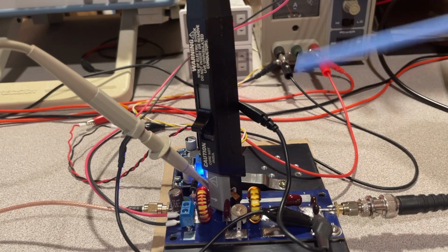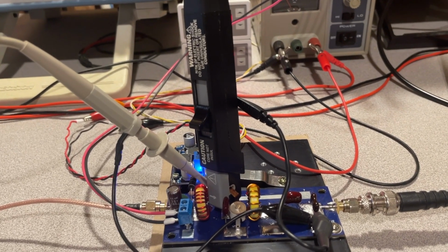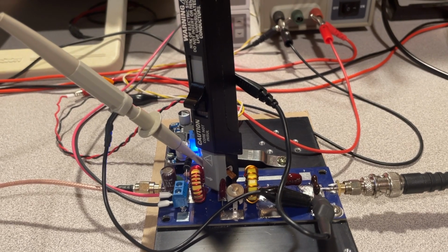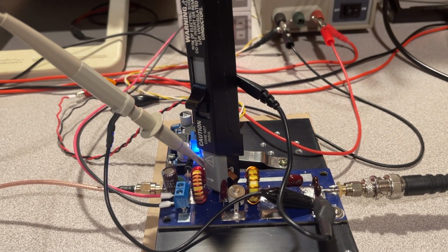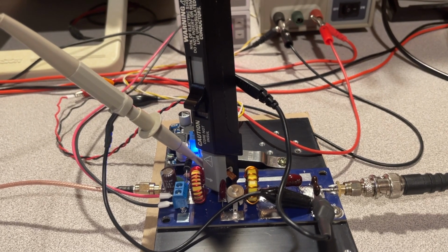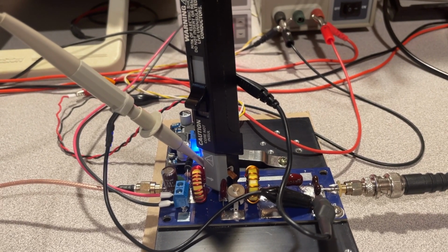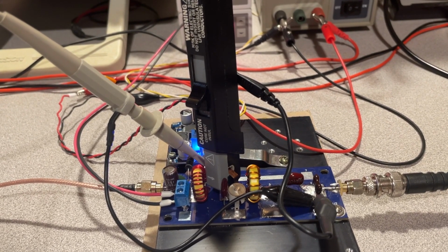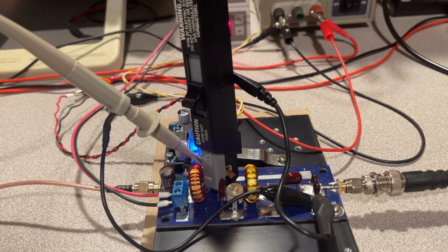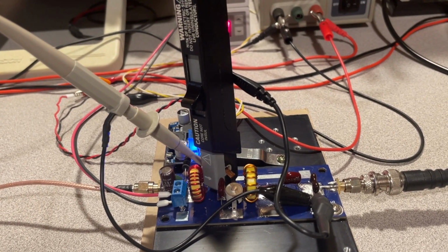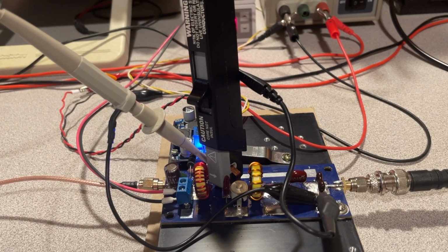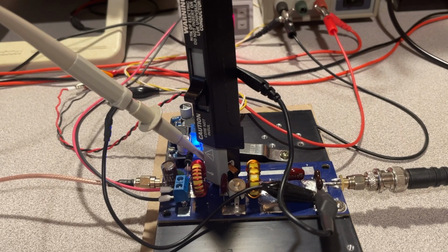And I mentioned in the other video that has to be a high Q inductor. So basically I was able to use a powdered iron core, and to reduce the resistance, the core allows me to use fewer windings to achieve the same value of inductance, and I used a heavier gauge wire. So remember, the Q is the ratio between the inductive reactance and the resistance, so you want the resistance to be as low as possible.